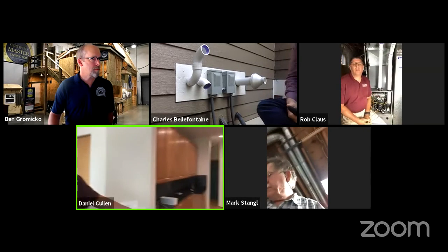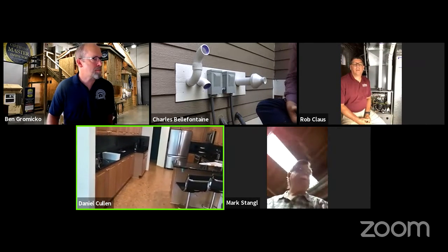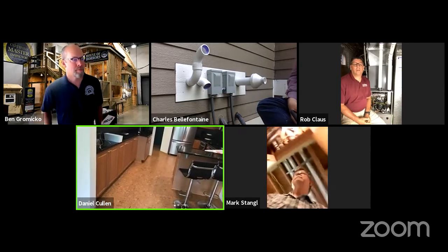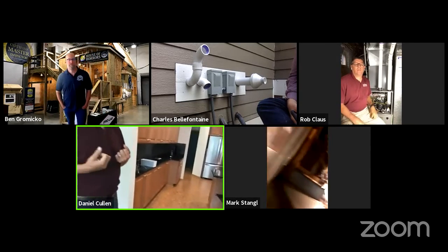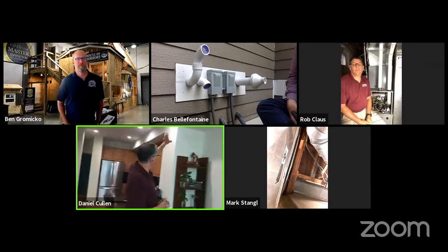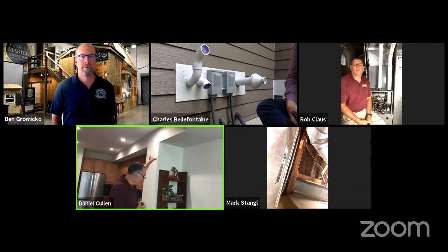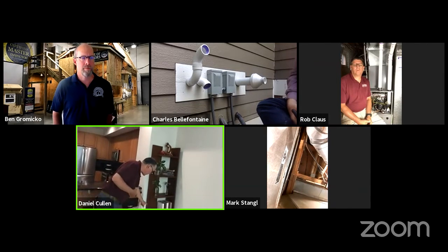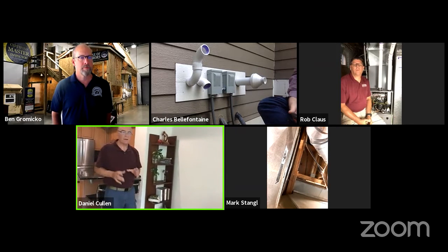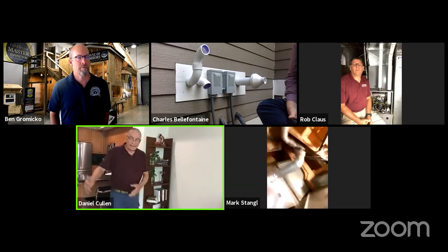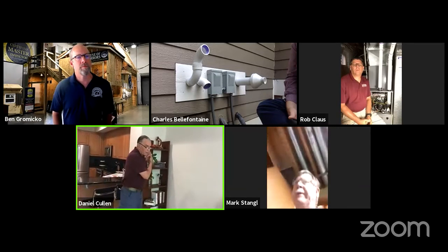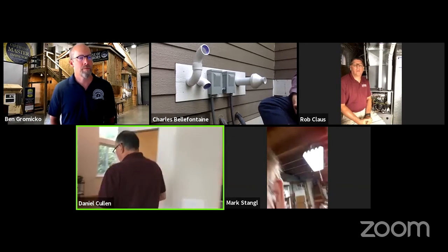So one thing we did was put in a cork floor over the tile floor in the kitchen. I didn't add any additional return air, although we have the capability here. We can come down, the unit is right above us. In conjunction with remodeling the guest bathroom, I'm going to bring a return air duct down here, probably an 8 or 10 inch round, right near the floor. Then in the wintertime, we're going to pull that cold air off the floor, get it back to the unit, recirculate it, and send it back out. Let's go upstairs and look at some of the equipment.